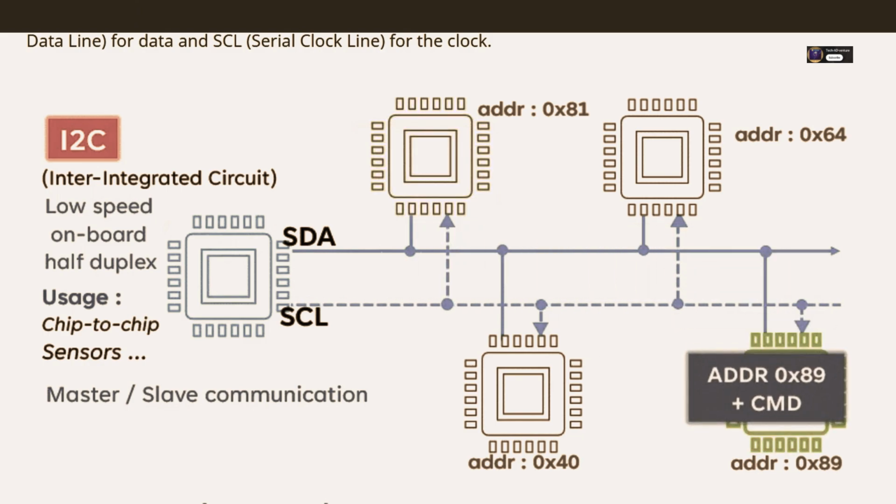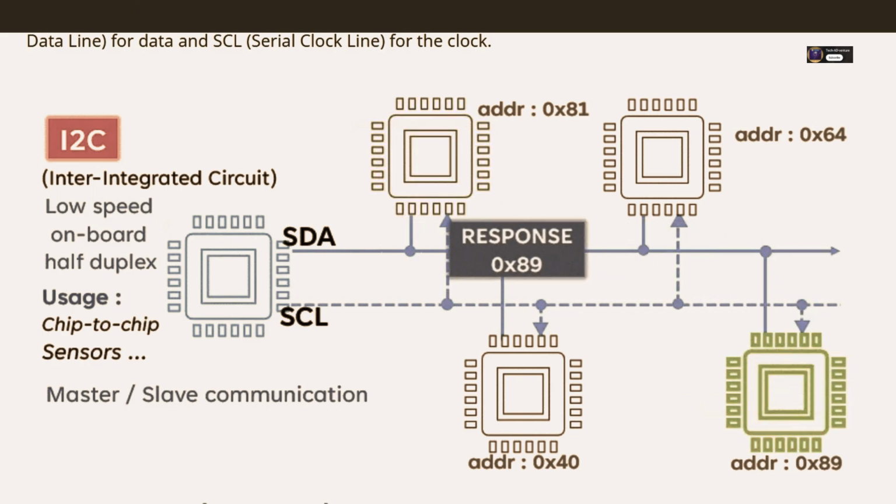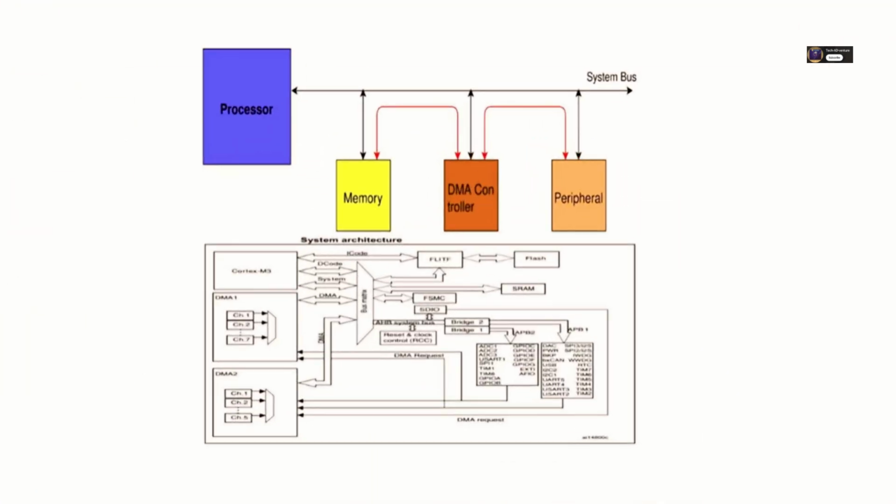Okay. And making it more efficient? For efficiency, especially on microcontrollers, using direct memory access, DMA, with the I²C peripheral is a big win. Many micros let the I²C hardware talk directly to memory via DMA. This means you can transfer blocks of data, like reading a whole chunk from a sensor, without the main CPU having to handle every single byte interrupt. Frees up the CPU massively. The CPU just sets up the DMA transfer, tells the I²C peripheral to start, and then DMA handles moving the data between the peripheral and memory automatically. It's great for high-speed data acquisition or just reducing CPU load in busy systems.